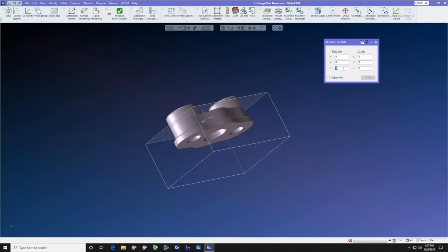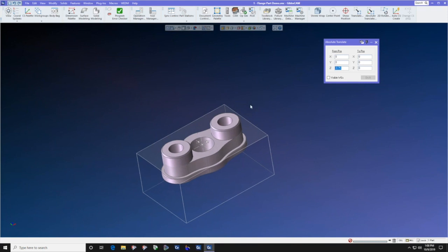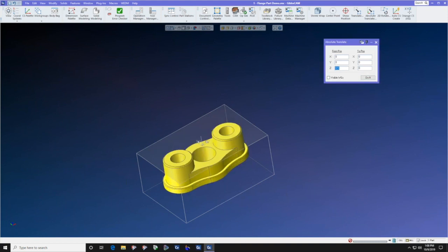I'm going to double click here, Absolute Z from, and I'm going to Alt click on the bottom of the part. Or should I Alt click on the top of the part? Depends on which dimension that I know. I know that's going to be 0. So it's at Z.5. I want it to go to Z0. I next click on the part, send the part to Z0.